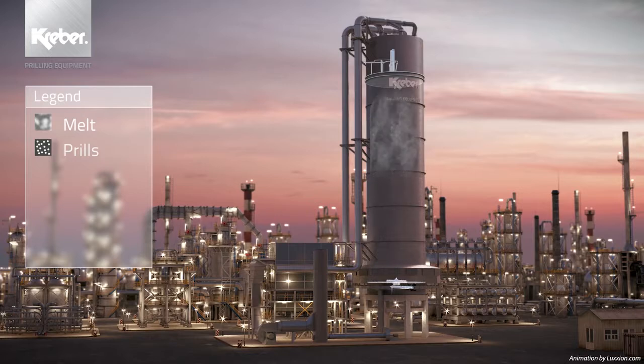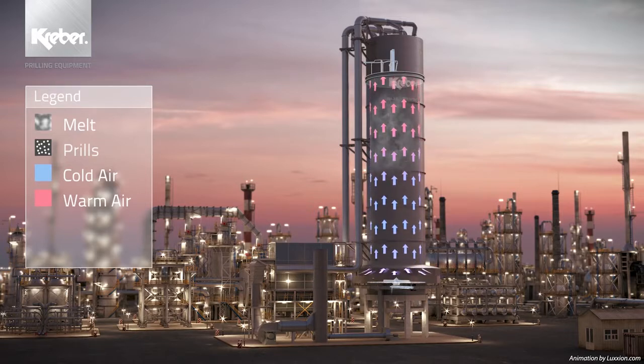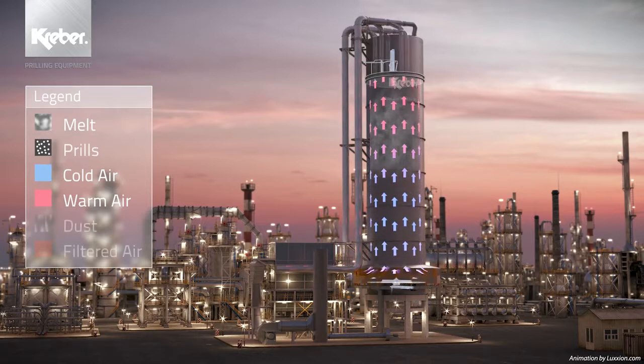The prilling of urea begins with the very accurate drizzle of melt droplets evenly spread across the cross-sectional area of the tower. Before reaching the bottom of the tower, the drizzle is cooled with purified air, which also allows a soft landing of the crystallized prills.